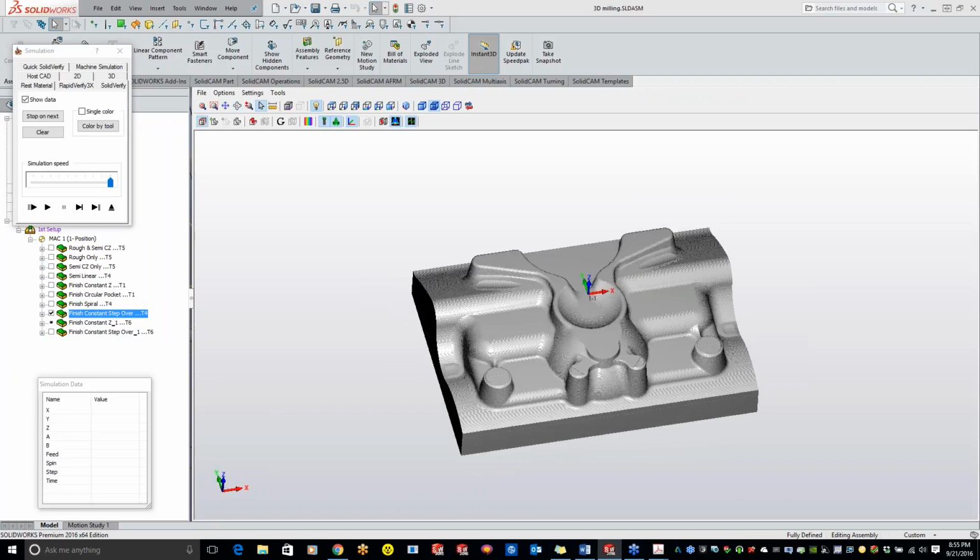All right, so now we want to clean up those flat areas. Go ahead and hit the play button here. Oh, actually, I told it to start from the center and work its way out. So we're probably better off starting on the outside and working our way in so we don't have that straight line going right through there. Oh, looks like that one did. I must have my chains going one direction going a different way.